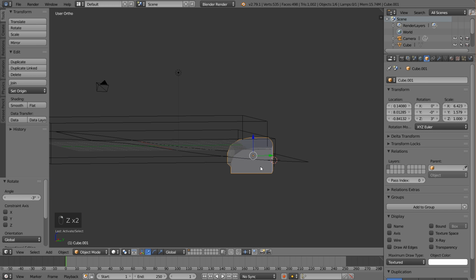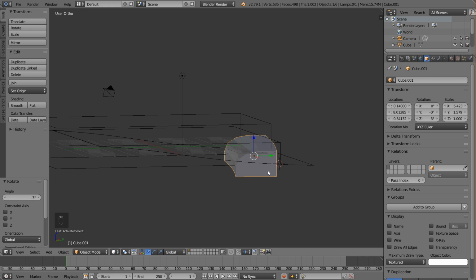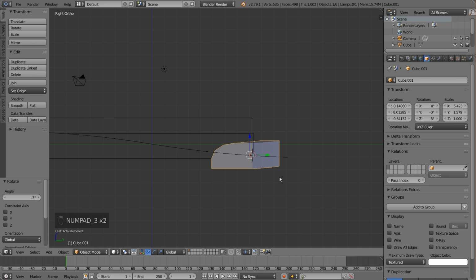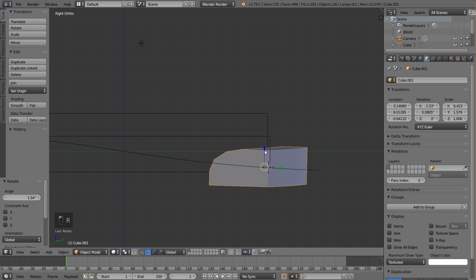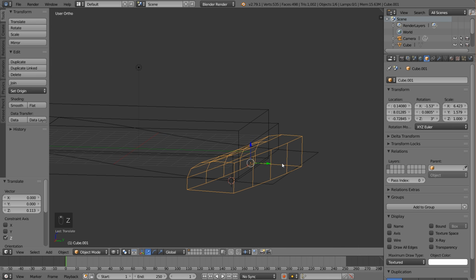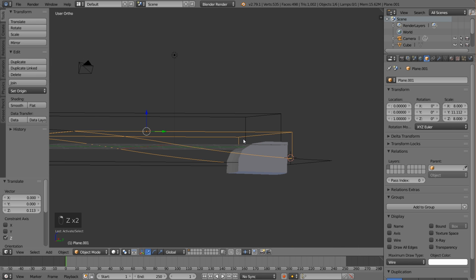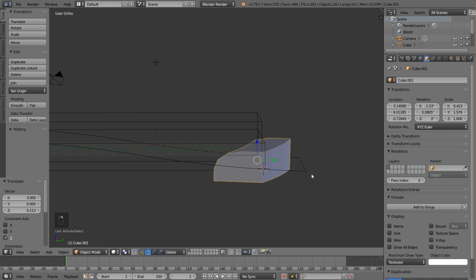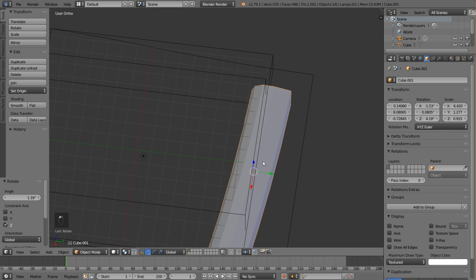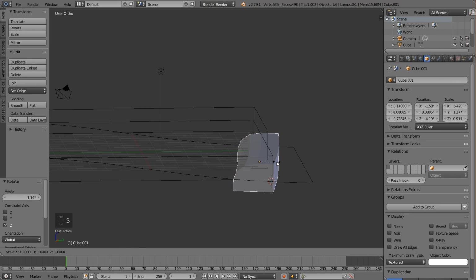All right, cool. So now with our splash obstacle here, let's set up a little bit of an animation so it will create some nice splashes. So first off, maybe I'll rotate it upwards just a little bit, but that should be pretty nice. Okay, and let me just check. Our fluid level is right there. So our splash object might be a little big. Scale it down a little bit maybe. Alright, just positioning it in there like so. That looks to be good, I think.